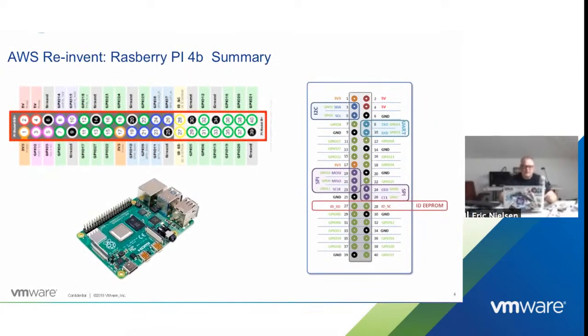That's what are on these pins. All the rest of these pins are what we would call GPIO pins, general purpose IO pins. What these pins allow you to do is send data or send power out and read power, right? I think they run on 3.3 volts. Most of these sensors run on 3.3 volts. You can send power down the line, or you can read what power is coming up from the line. And then you can do that in time sequence, fast or slow. That ends up being pulses, which is actually then data. So a sensor can send pulses down any of these GPIO pins, and you will be able to read that data.